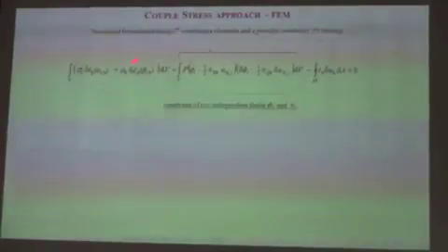So there's another tricky FE approach when you want to use C0 continuous elements. You have to use a penalty constraint like parameter called P. Now the variational formulation is that the strains depend on the first gradient of displacement, and the rotation gradient still is dependent on a first gradient of the rotation.